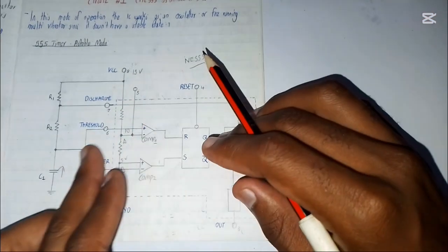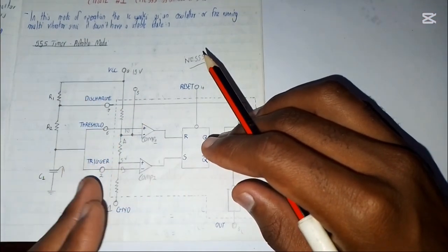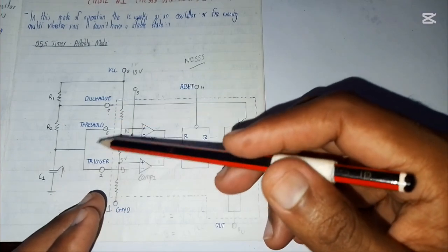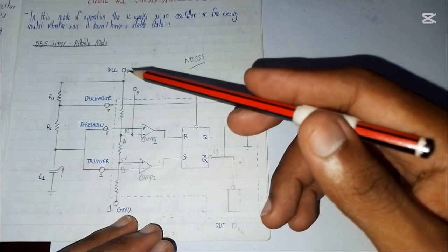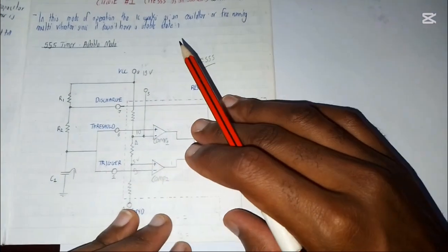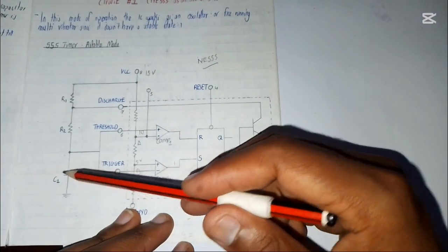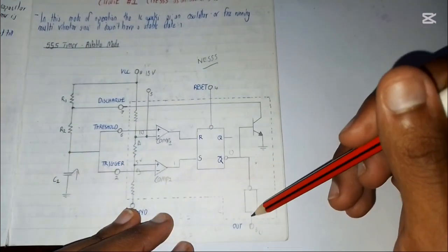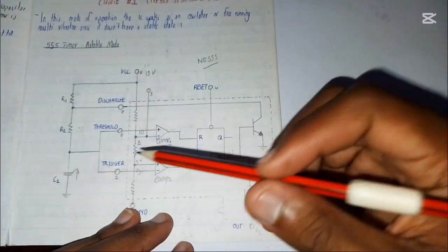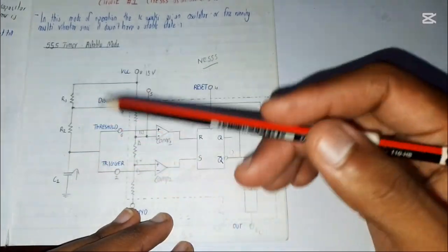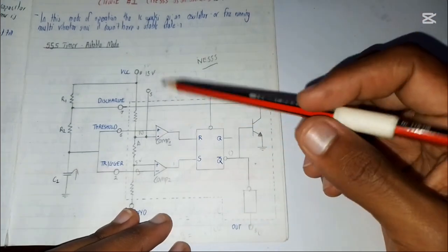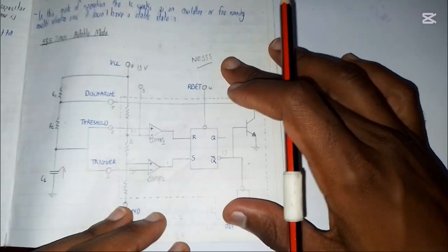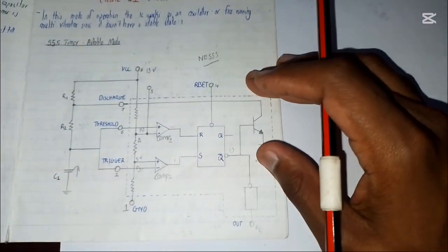So the external circuitry you're seeing here is how you can connect an NE555 to operate in an Astable manner. The circuitry consists of a capacitor, which depends on you, on how you want your pulses, the frequency of your square wave in the output, and two resistors which are mostly identical. And those are just what you need in order to make an NE555 operate in oscillator mode.